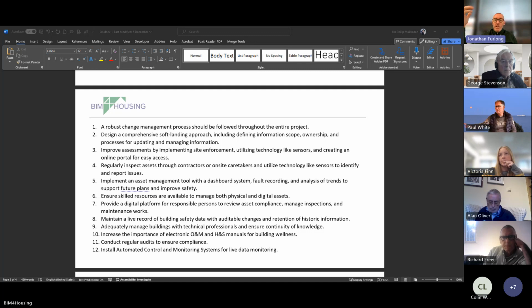But things like smoke control doesn't get covered. AOVs won't get covered. Even alarm panels won't get covered. An evac system will get covered, because again, that's a firefighting system for firefighters only. But door control and other stuff like that, none of that has to get checked. So I think people need to be realistic on what is required and where we're going, and even the cost of doing those monthly checks is a huge uplift on current situations.